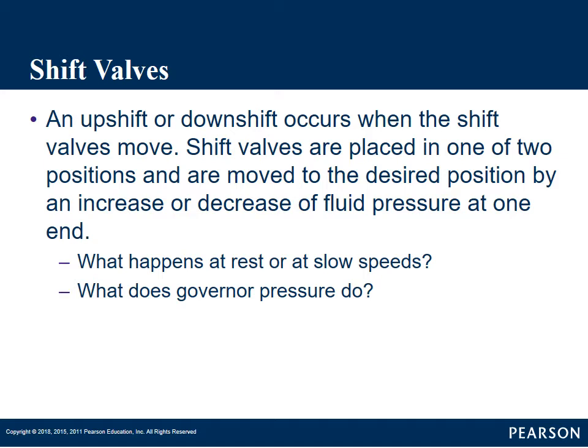That's why when you're accelerating harder, shifts are later. When you're accelerating lightly, shifts are earlier. They do that again because under heavier loads, we need to make sure that we have more pressure applying those clutch packs.